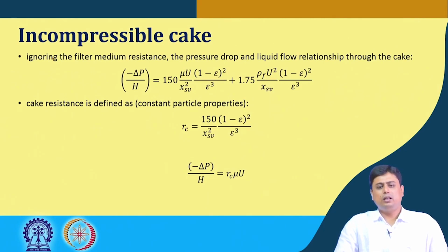So focusing on the cake filtration, we have mentioned that this cake basically consists of fine particles of a certain voidage. Since this is a packed bed of particles, quite clearly there will be void spaces through which the filtrate, or suspension, can pass.